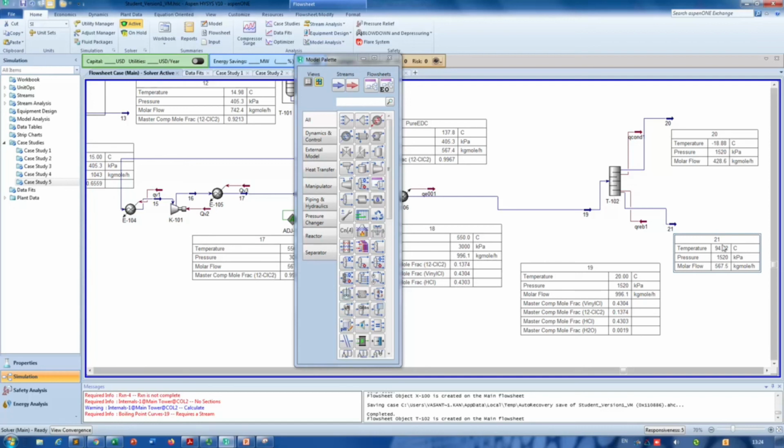So whatever we are doing, we are using different methods. We use the component splitter to get some initial values for the reboiler temperature and condenser temperature, and then we use those values in the shortcut distillation column, and then we got new values for the reboiler temperature and the condenser temperature, which is minus 18.8. Okay,